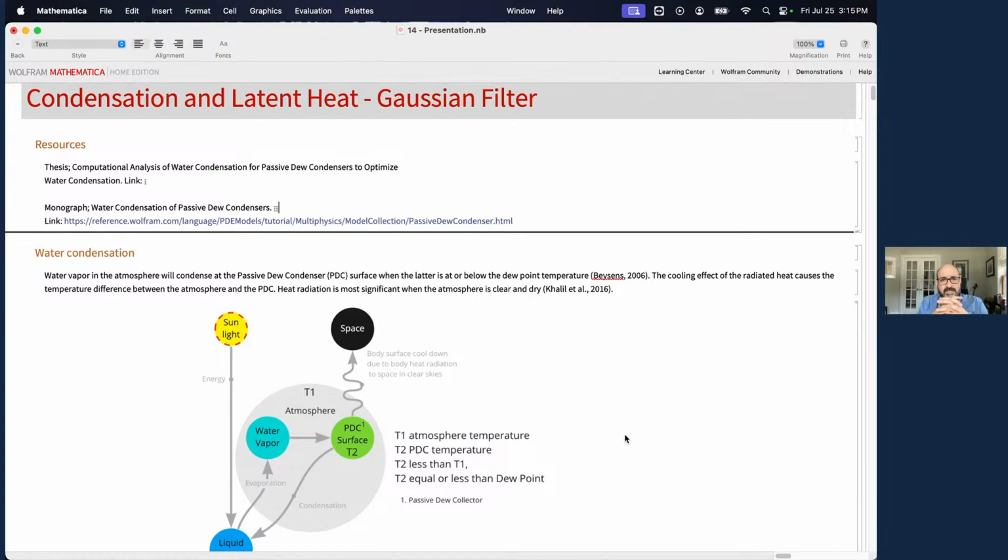I think that's going to be useful for you whenever you see something that is very time consuming, very demanding, that is going to take a couple of days to simulate. There are some strategies that you should use to save your data, keep it in a separate file, and reload it, so you don't have to rerun your PDEs. Some of these PDEs are very taxing for computers. I started this on the Mac M1 processor. I'm on the Mac M3 processor.